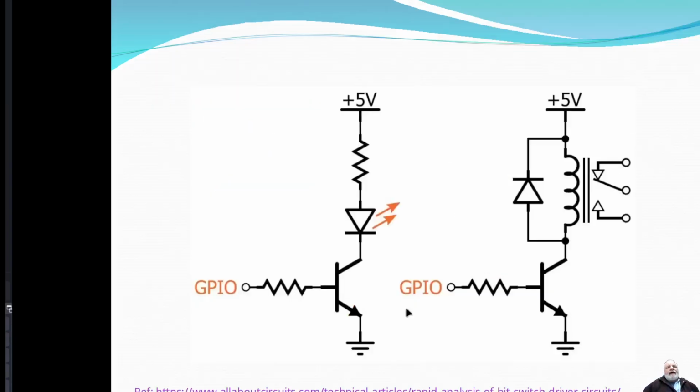Alright, so here we have a typical switching circuit with the transistor, again, kind of like the ones we looked at before, but here we have a BJT. The idea is we have this GPIO connection from a Raspberry Pi or digital output, for whatever device this is, and we need to know what the maximum voltage is. What is the voltage when this is a 1? If it's a silicon BJT, you're talking about a 0.7 volt drop here.